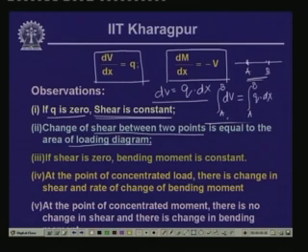Now, this gives us that integral dV from A to B is basically shear force at B minus shear force at A. So, the differential shear force between B and A is nothing but q dx, which represents the area of the loading. As you can see on the beam, when we have the distributed load q, over the length dx this gives the area of the loading.